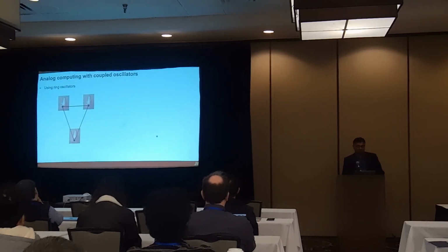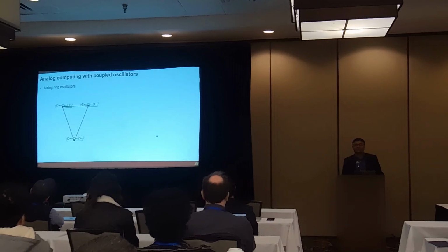So how does this work out? We have these coupled oscillators. Initially, they were metronomes. Now we're going to use ring oscillators. And ring oscillators, as you probably know, are basically just a bunch of inverters connected in a cycle with an odd number of inverters, and it's going to cycle forever.